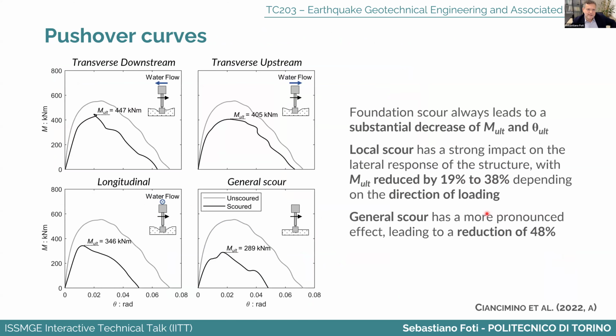This is an example of results that point out the different behavior of the unscoured foundation against the scoured foundation. Obviously, this large difference that we observe in terms of behavior of the foundation has a very strong impact. Remember also that this implies that we are changing the frequency of the structure, so the structure is going to be quite different in terms of its dynamic and specifically seismic response.